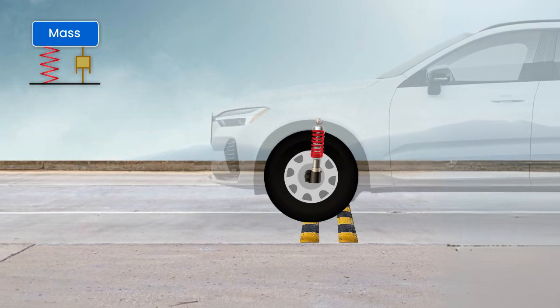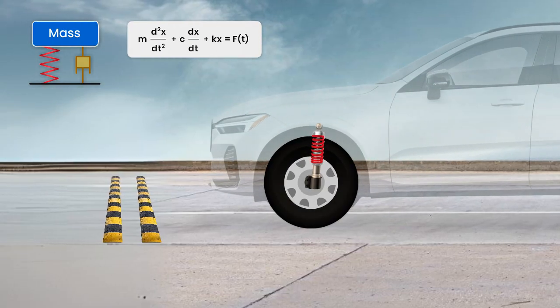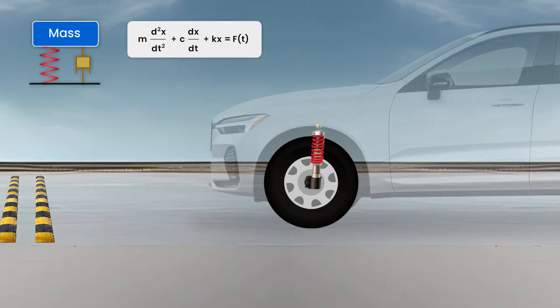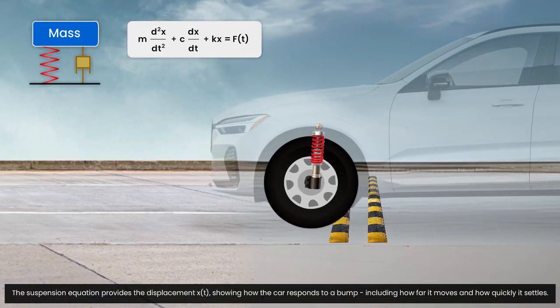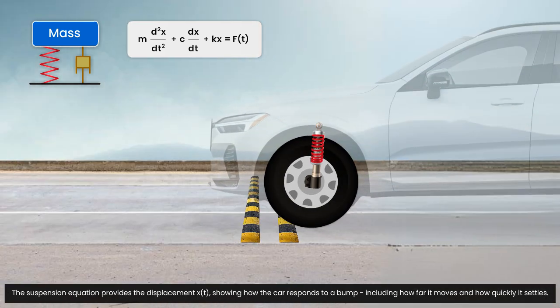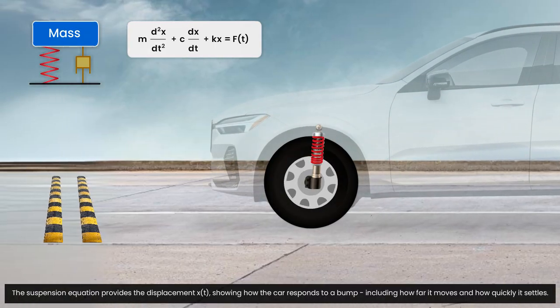This system is governed by a second-order differential equation of the form m d²x/dt² + c dx/dt + kx = f(t). The suspension equation provides the displacement x(t), showing how the car responds to a bump, including how far it moves and how quickly it settles.